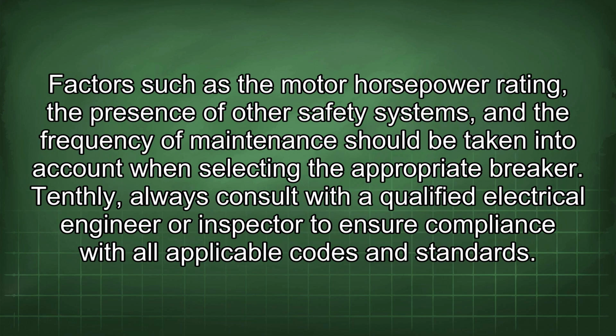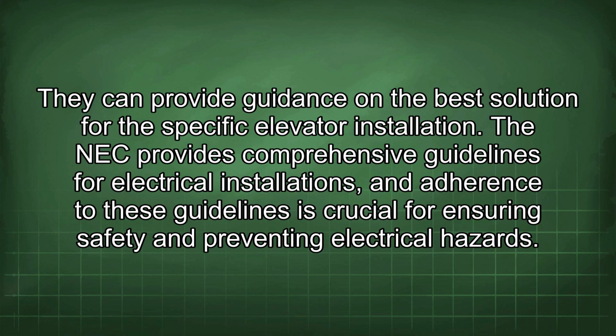Ninthly, the specific requirements of the elevator system should be evaluated. Factors such as the motor horsepower rating, the presence of other safety systems, and the frequency of maintenance should be taken into account when selecting the appropriate breaker. Tenthly, always consult with a qualified electrical engineer or inspector to ensure compliance with all applicable codes and standards. They can provide guidance on the best solution for the specific elevator installation.